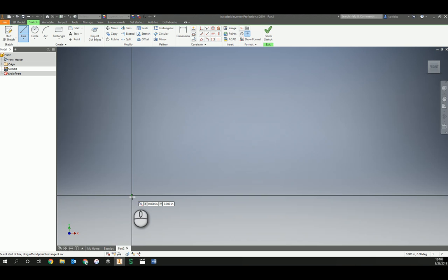Now it's important to anchor everything to the origin point, and you can see how the mouse should turn green here, the little dot. I'm going to click and let go. That's important. Here's my line. Now if you notice, as I bring it down to the axis, it should just snap on me. There, it snapped. So you can see how it'll just pop to the axis as the computer's pretty smart and knows mostly what you want to do.